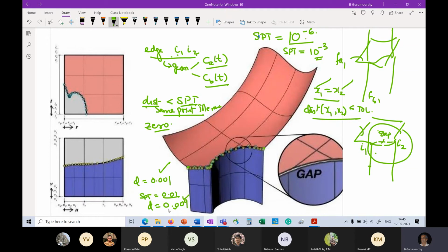Right? But when you take this same object and bring it to a CAD system that takes this to be the same point tolerance, it will not recognize these two to be the same point, and therefore it will treat them as two different curves, and you will have a gap, and it will say that the solid is invalid. And so this remains a big problem, right? While this is a solution that most CAD systems use to avoid the invalidity problem, right? Nevertheless, it remains an inelegant solution, because now you are carrying two representations for the same entity, depending on where you are computing it.